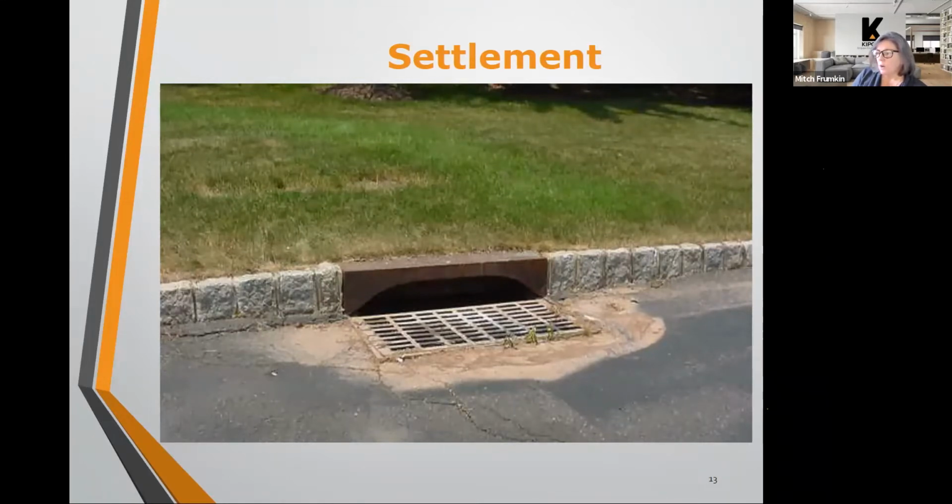So as we come out to do that visual evaluation at the beginning of the project, we can't always see the condition. We can get a general idea by peering into the inlet, but until that steel is removed and that frame is removed by the contractor, the underlying problems in the catch basin structure are not more visible.